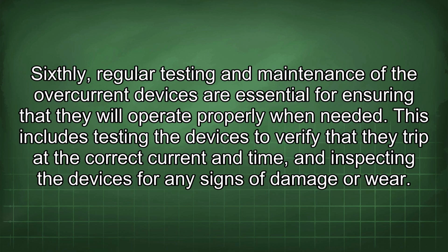Sixthly, regular testing and maintenance of the overcurrent devices are essential for ensuring that they will operate properly when needed. This includes testing the devices to verify that they trip at the correct current and time, and inspecting the devices for any signs of damage or wear.